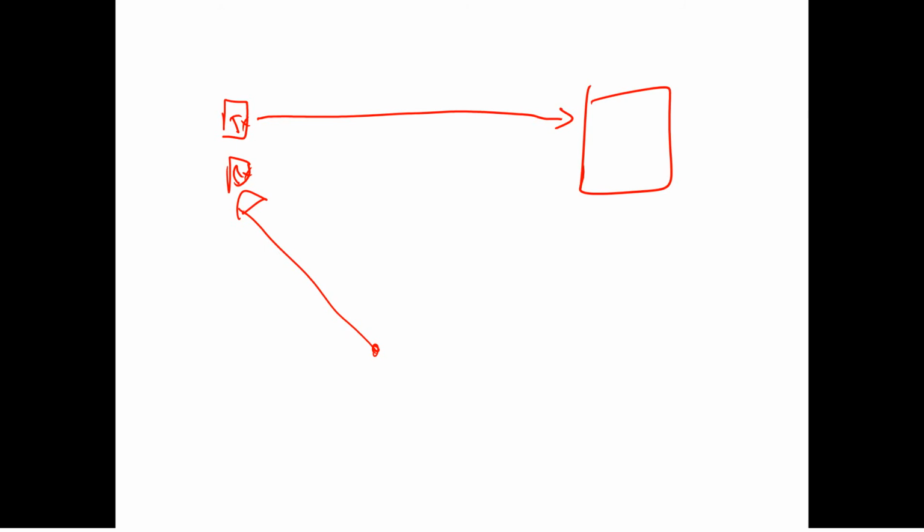The other problem is that there's going to be 2 robots running the course, and both of these have the same sort of system on them, with the transmit and receive. So if one of you transmits at some time, and this other robot is also transmitting at another time, that transmit pulse will be seen by the other robot, and it'll generate a false distance signal.